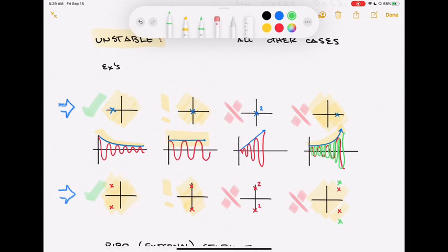Both of these cases that we just did are unstable. The weird, quirky one, the one that you might first look at and think should be marginally stable because you don't see any poles in the right half plane, is when we get poles on the omega axis, but they are repeated. Let's take a look at this first one. This first one is a lot like the one to its left. I just repeated one of the roots.